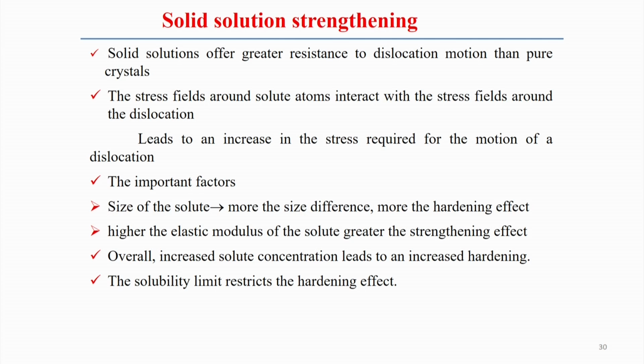If we see, solid solutions offer greater resistance to dislocation motion than pure crystals, because in pure crystals the lattice arrangement is almost perfect in the absence of any kind of defect. Here we are assuming the defect is present only as solute atoms. In the absence of solute atoms, the resistance to dislocation motion is very low in pure metals.